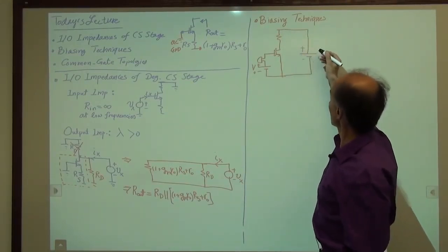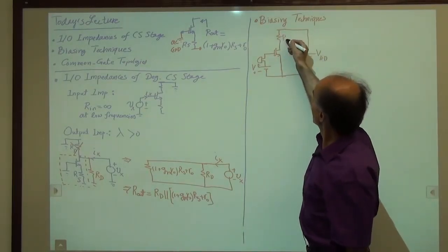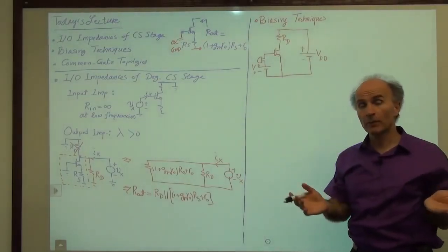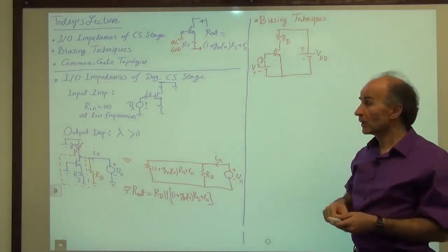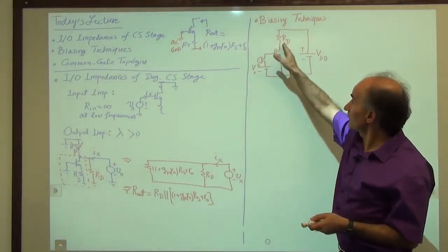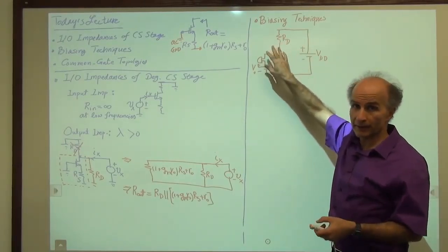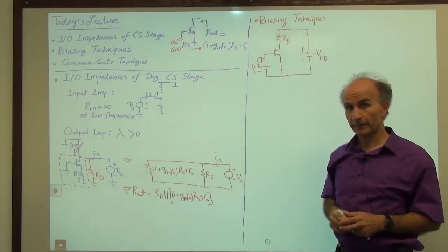So that's what we call, for example, VDD. Okay, so this circuit, as shown, can be properly biased. In the absence of a signal from the microphone, you have a certain voltage here, you have a certain current here. Hopefully this VDS is not too low, the device is in saturation, everything is good, we have an amplifier.